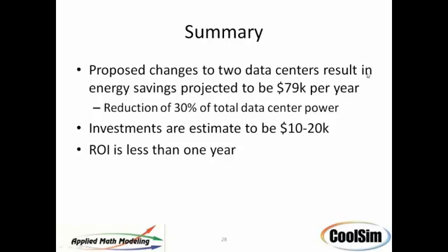Right. Another thing to point out is that if you cannot change the airflow rate, and if you cannot increase the supply air temperature, it doesn't matter what air management measures you implement in your data center. It's going to give you nothing. The key is that you must be able to increase the supply temperature and/or reduce the airflow rate. It's interesting you said and/or, because if you simply reduce your airflow rate, your return air temperature will actually go up and your efficiency will go up. But you might not be able to do that. Yeah, that's right.